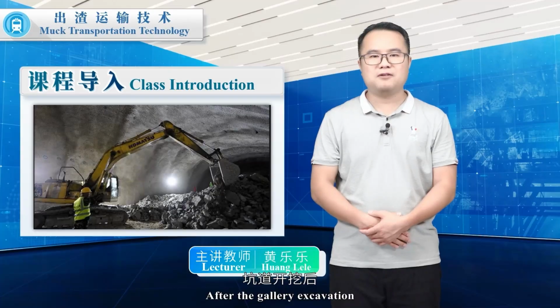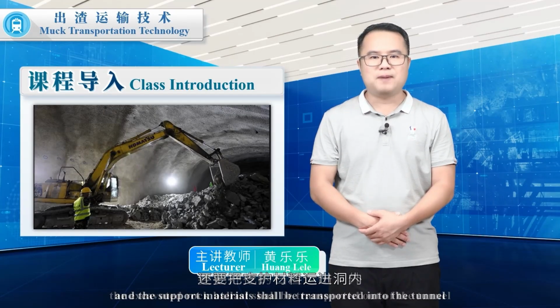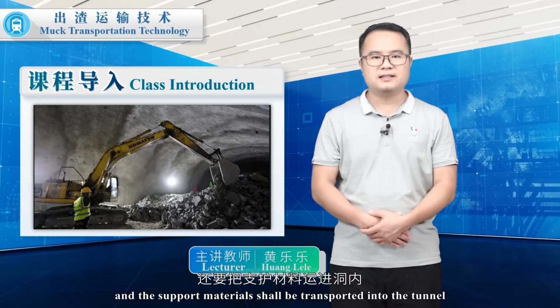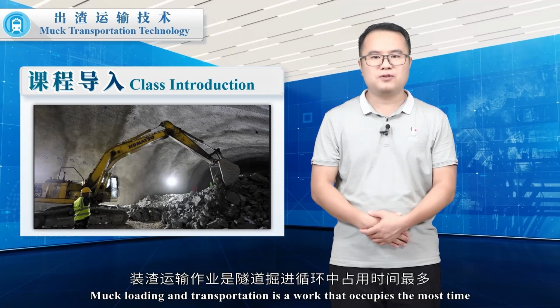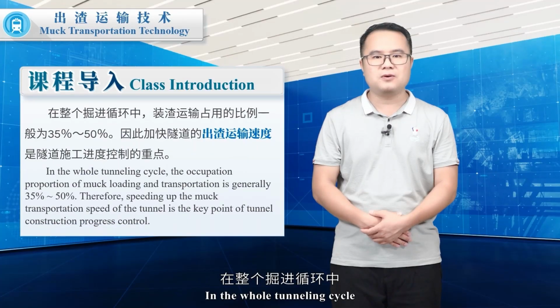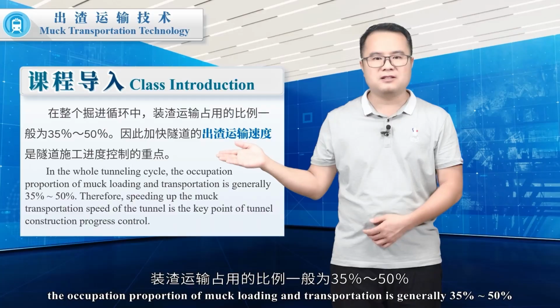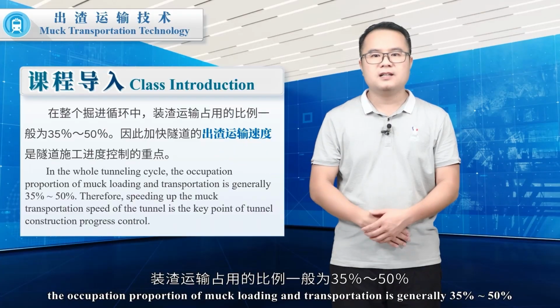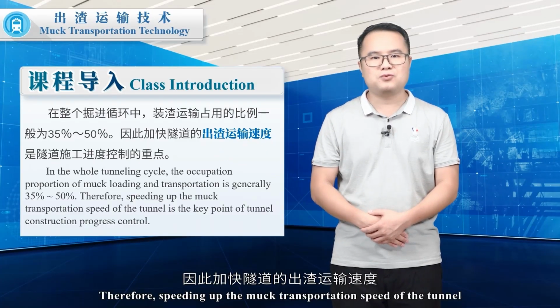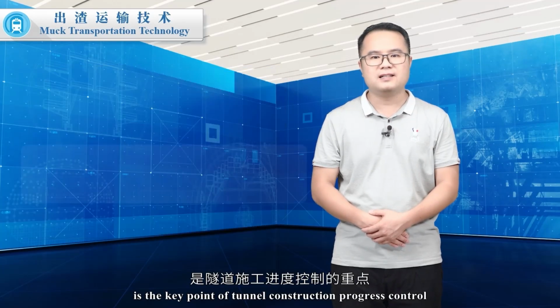After the gallery excavation, the excavated rock ballast shall be transported out of the tunnel, and the support materials shall be transported into the tunnel. Muck loading and transportation is a work that occupies the most time in the tunneling cycle and interferes with other operations greatly. In the whole tunneling cycle, the occupation proportion of muck loading and transportation is generally 35%-50%. Therefore, speeding up the muck transportation speed of the tunnel is the key point of tunnel construction progress control.